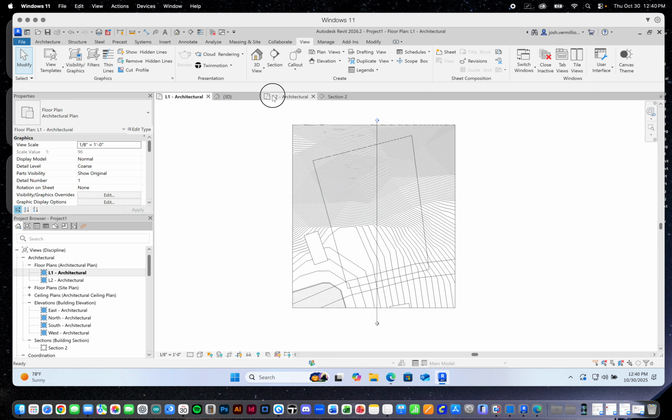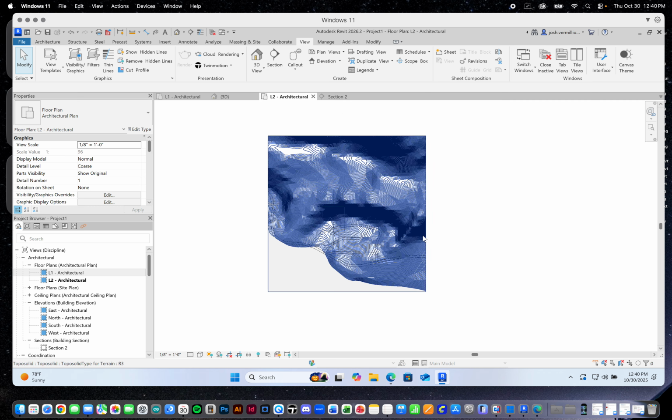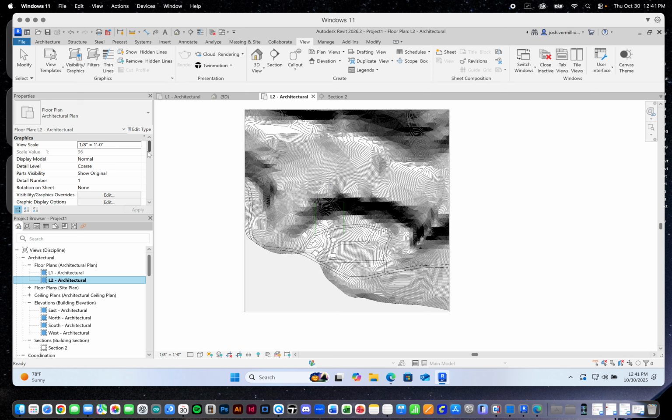All right, we can do the same thing for level 2, right? Floor plan 2, right? Every time I open something here, it remains open up here as a tab, so I can start to toggle back and forth between different orientations and drawings. So for level 2, I can again scroll down, look for the scope box, set it to Josh's scope box.